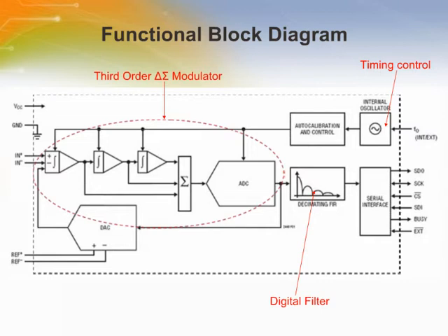The LTC2440 performs offset and full-scale calibrations every conversion cycle. The advantage of continuous calibration is extreme stability of offset and full-scale readings with respect to time, supply voltage change, and temperature drift.